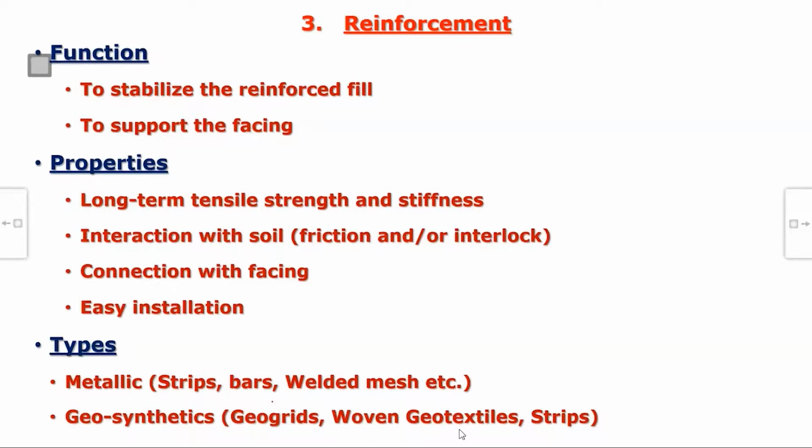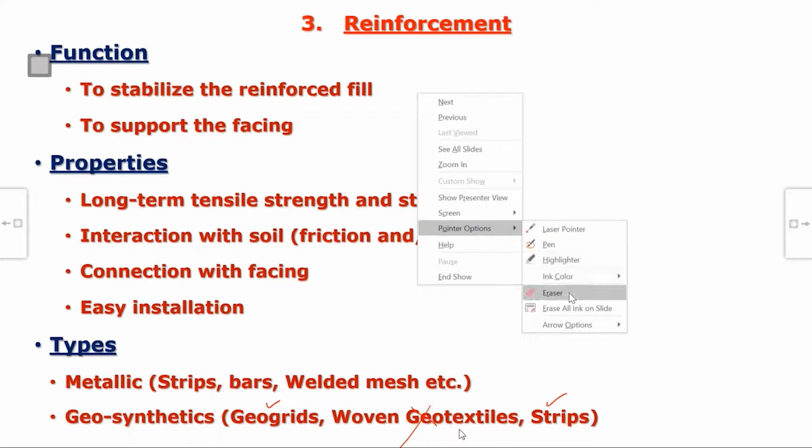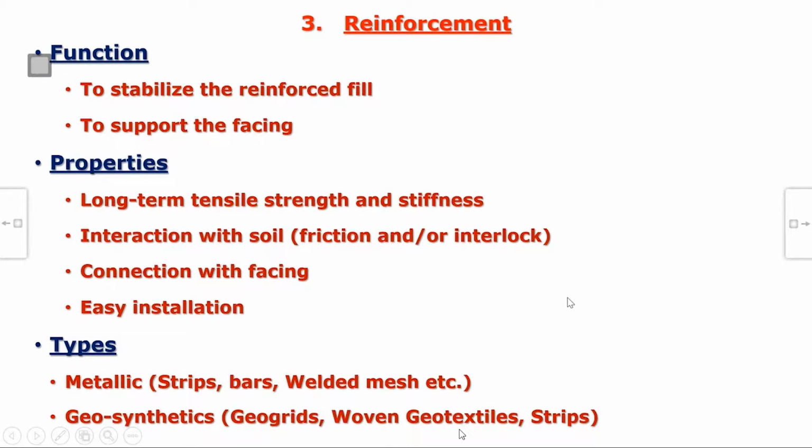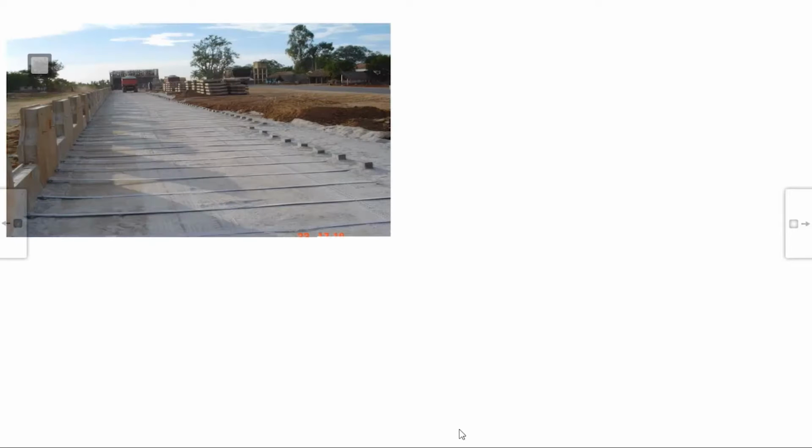Yes, sir. Thank you. Geogrid and strips are most commonly used now. The advantages of why they are used: number one, they are non-corrodable. They do not get corroded. Their coefficient of creep is very, very less, they are very light, very easy to handle, and you can manufacture them in any strength. As I told you, they look almost the same, 40 to 100, in physical appearance. Only the input material and some process change. So they have become very popular nowadays.